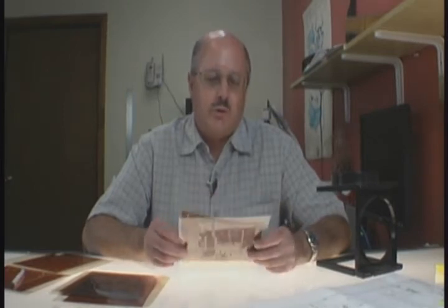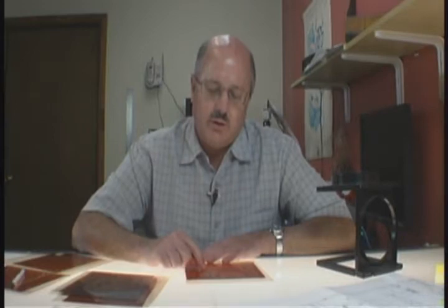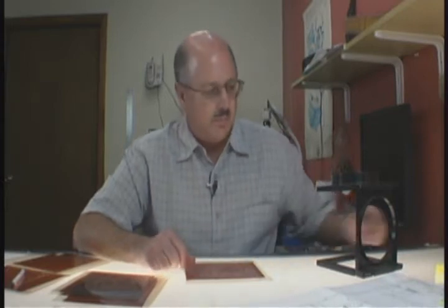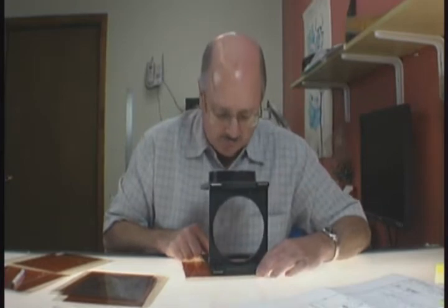Next step is to bring those to the light table and overlay the negative of the new Gerbers to a positive of the customer's original. The reason we use the diazo film is that it's transparent, and any slight overlapping causes dark spots on the film, and it's easy to detect differences between the two films. The film is examined under magnification.